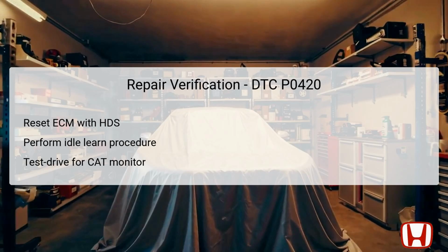During this test drive, ensure that the engine coolant temperature exceeds 158 degrees Fahrenheit, 70 degrees Celsius, and maintain specific driving speeds as previously discussed. Check the OBD status to confirm whether the catalytic monitor condition indicates OK for successful verification.